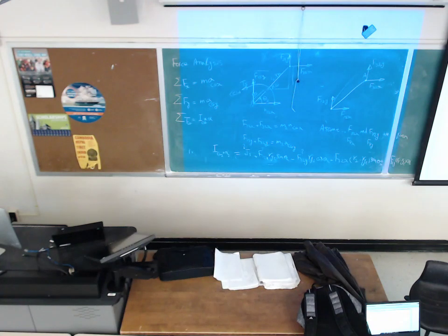And what input torque? 9. And each link is going to have its own 3 set of equations. We can solve 9 equations by 9. So just to do the force analysis, we would have to start from the displacement, then do the velocity, and the acceleration. And that gives us the acceleration, which would cause the force.